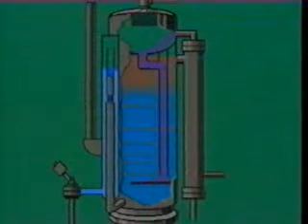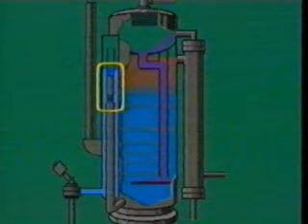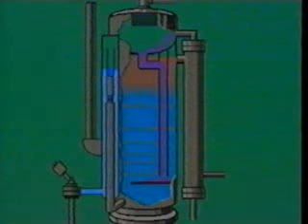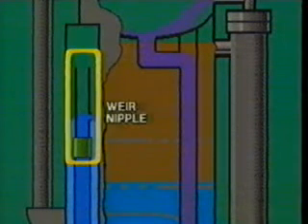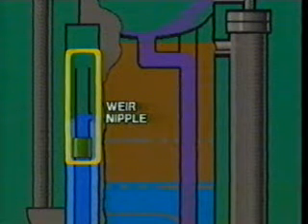To vary the height of the oil-water interface, the height of the pipe through which water enters the siphon must be changed. It depends on the design of the system. Lowering the siphon pipe lowers the oil-water interface, and raising the siphon pipe raises the interface. Some treaters use an adjustable siphon, or weir nipple, to change the water level. On these, a 1-inch adjustment of the nipple will move the interface height about 4 or 5 inches.